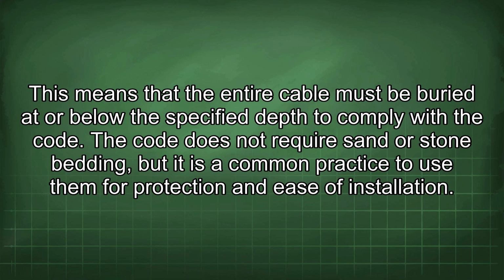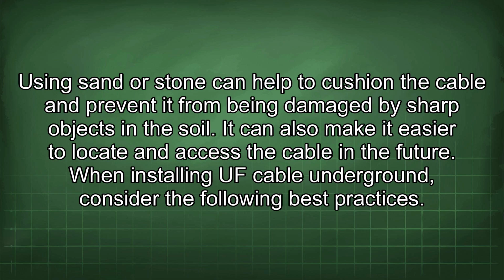The code does not require sand or stone bedding, but it is a common practice to use them for protection and ease of installation. Using sand or stone can help to cushion the cable and prevent it from being damaged by sharp objects in the soil. It can also make it easier to locate and access the cable in the future.